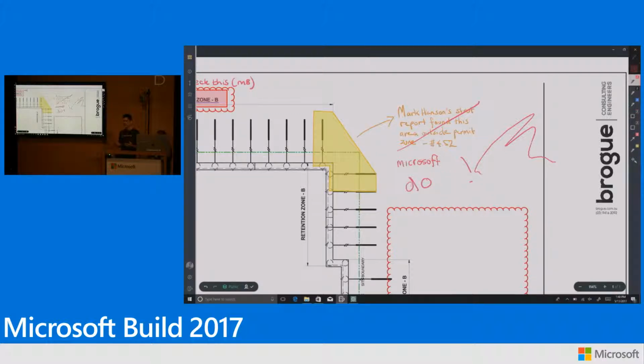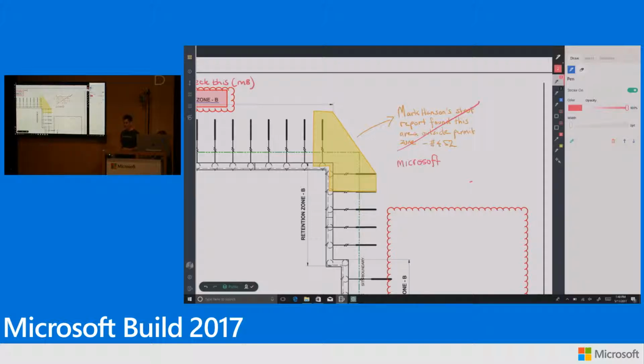But then what do we want the user to do next? Well, there are a number of UX things that we can provide, such as you might have noticed that we're drawing attention to the top right-hand corner. So we're spotlighting an area where we want them to go next. And if I tap that, it'll open up into a tools blade where this is the next point of action where we want the user to explore. And so they can go through the application in a top-down approach in the tools blade and select the tool that they're after. So say if I'm after a cloud revision tool, then I can choose that. I can adjust the width of it.